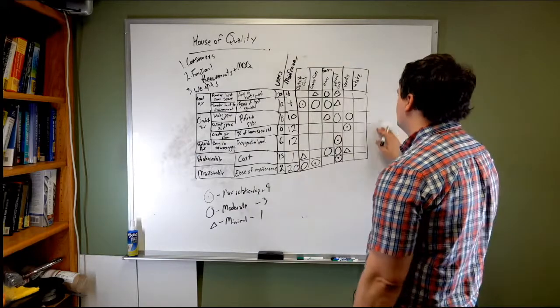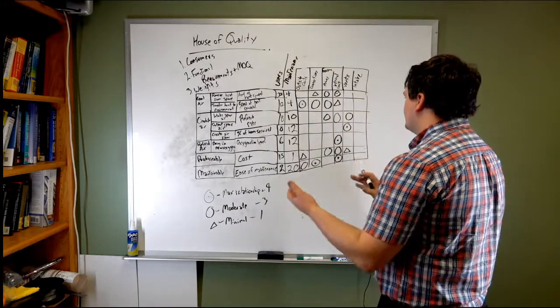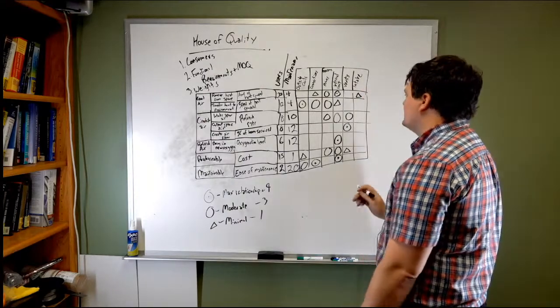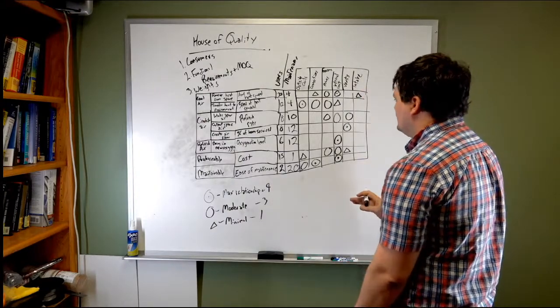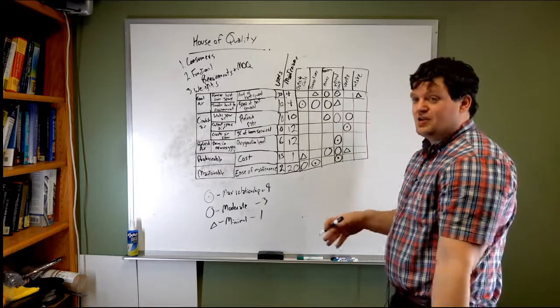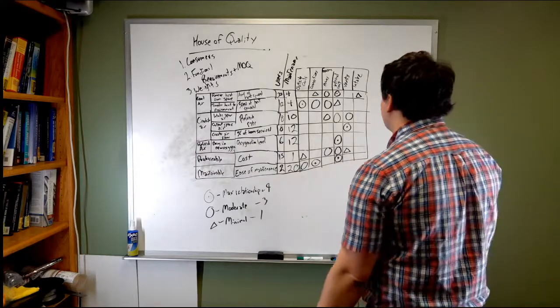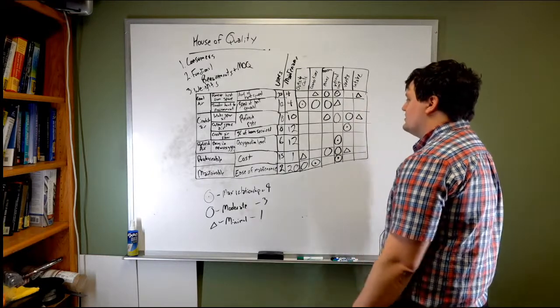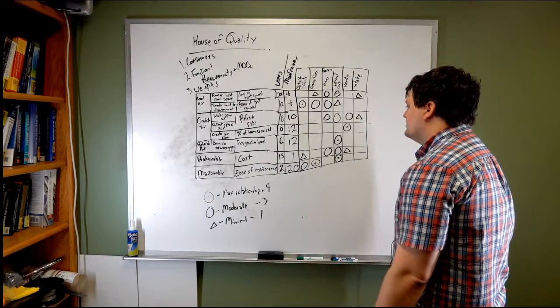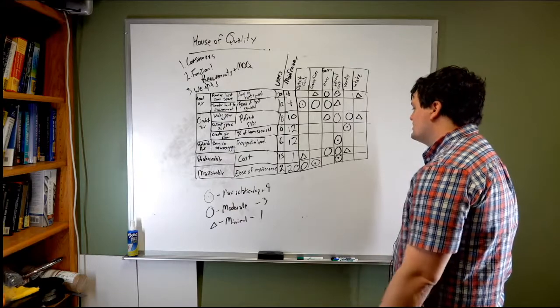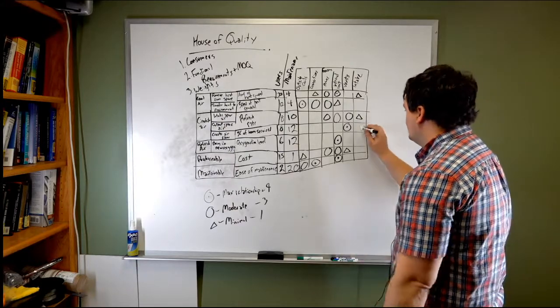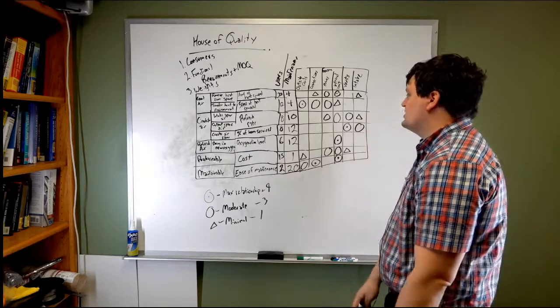Similarly with intake that comes from the house itself, you're going to have a small relationship to the amount of heat that's removed. Depending on where you put that intake, you may or may not get very much heat you're actually taking out of the house. It is going to have a relationship on the refresh rate. Probably not on your oxygenation level, probably not on your cost either. But it will have an impact on the percent of your home serviced.